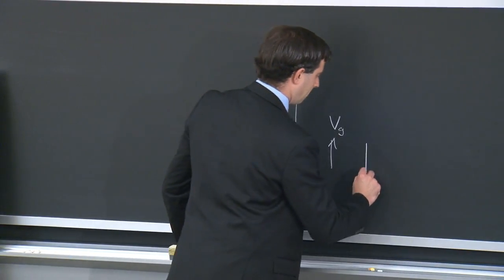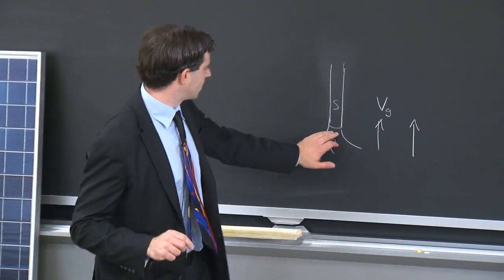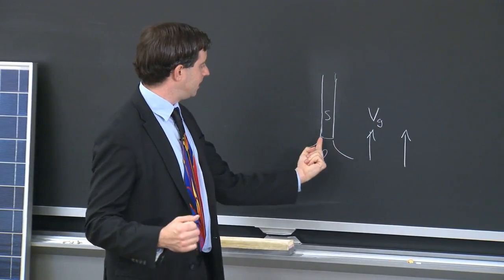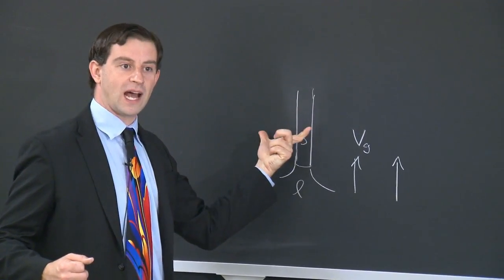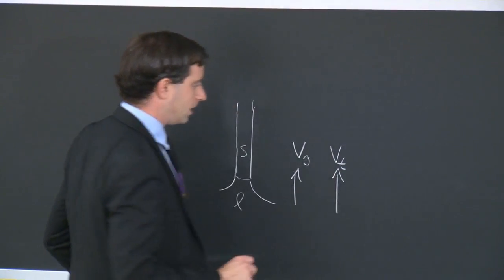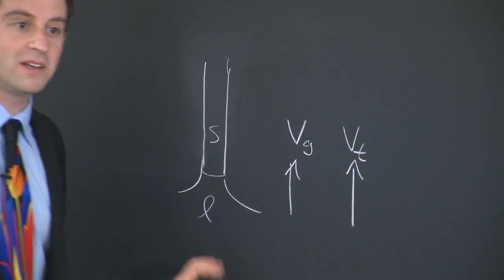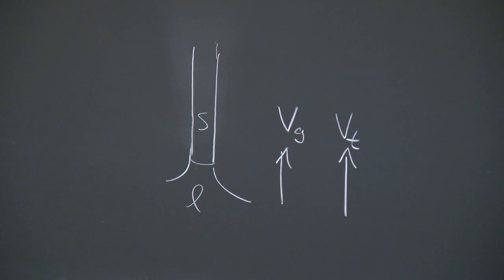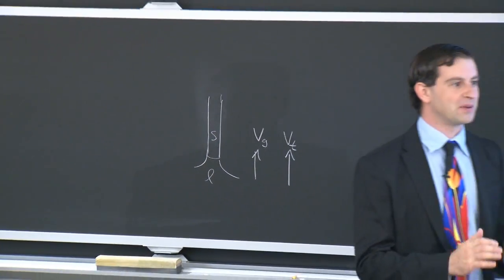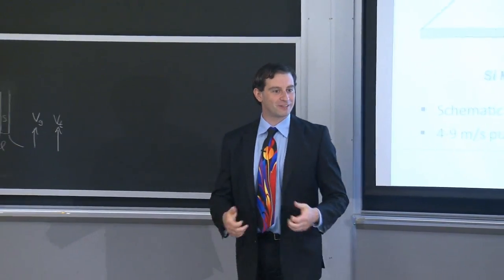And the direction of latent heat of fusion extraction. So you have liquid silicon solidifying here. During the solidification process, there's heat released. And that heat has to be conducted up the solid and then radiated outward from this thin ribbon. So the direction of heat extraction is also parallel to the direction of growth. What that means is the growth velocity will be limited by the speed at which you can extract heat up the ribbon and then radiate it outward. So there are many ideas tossed around about potentially growing in media that are able to extract heat faster than the radiative transport.